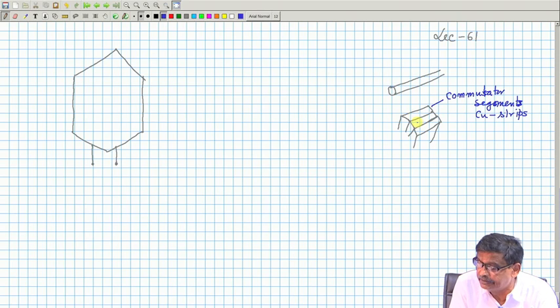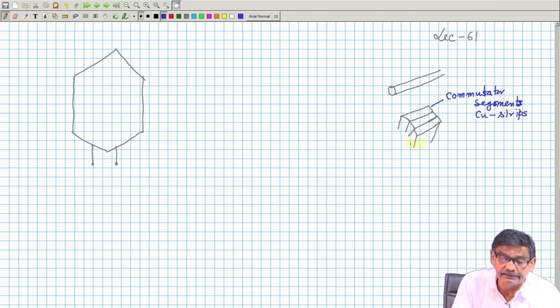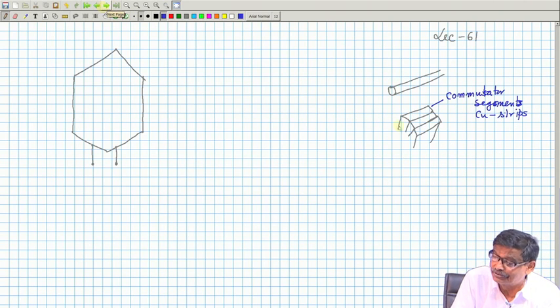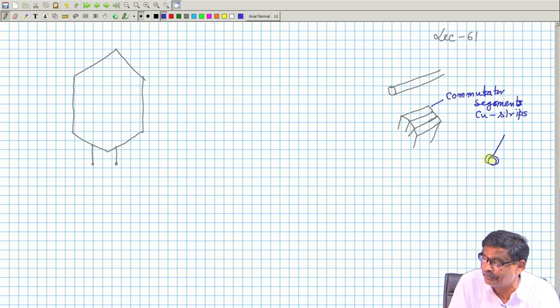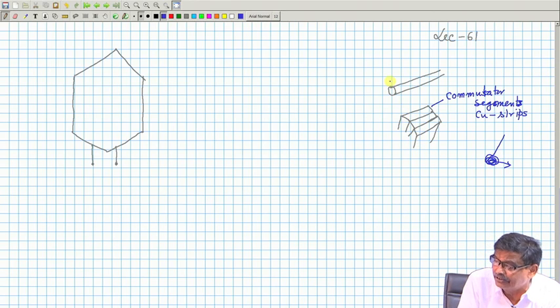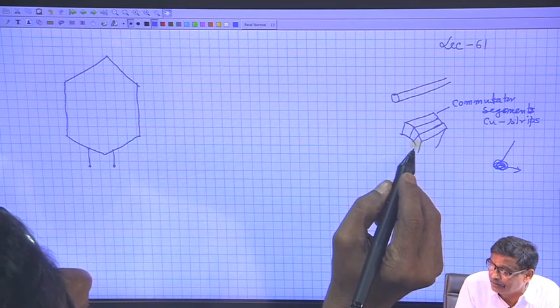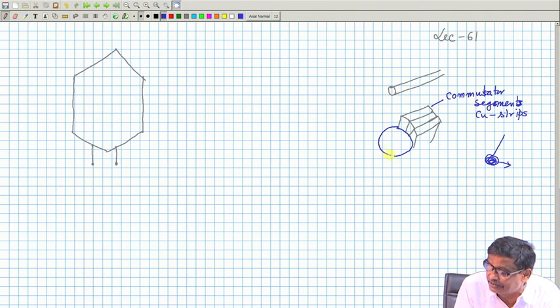But each copper strip, there will be as many commutator segments as the number of slots, because the number of those circular things we have seen is equal to the number of slots. So, those thick lines we drew previously, these I am telling, these are the copper strips. In actual machines it is done like that. Okay. I have not brought that armature winding today, unfortunately, next time I will show you, but this is on the shaft of the machine, it will be inserted. This way it will go, and this is the shaft of the machine.